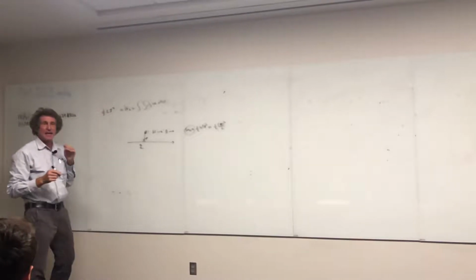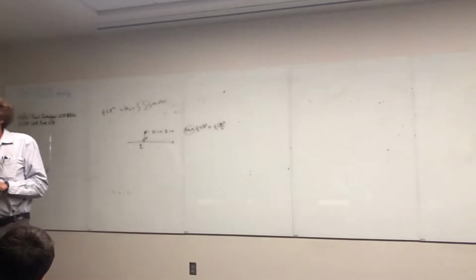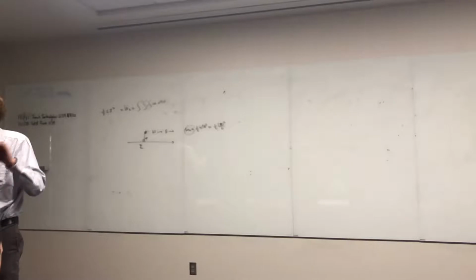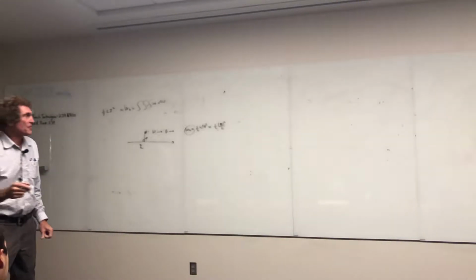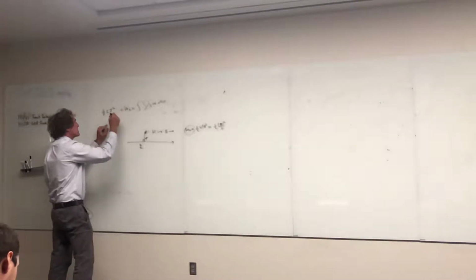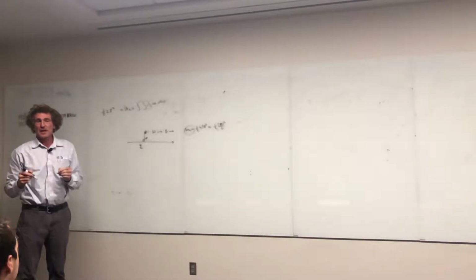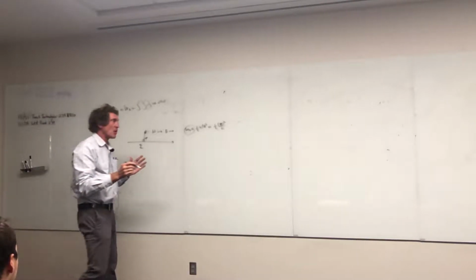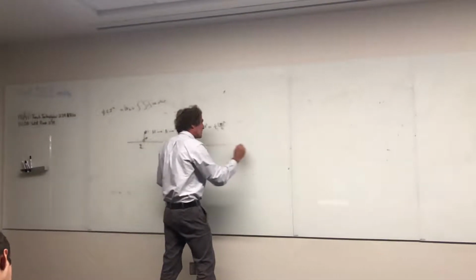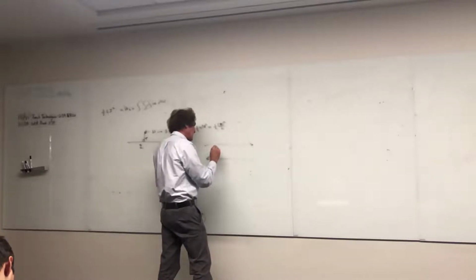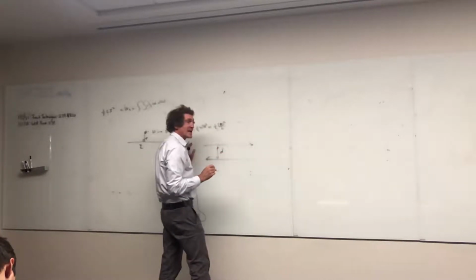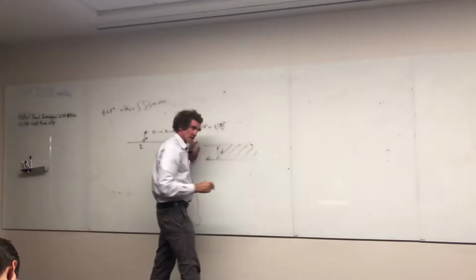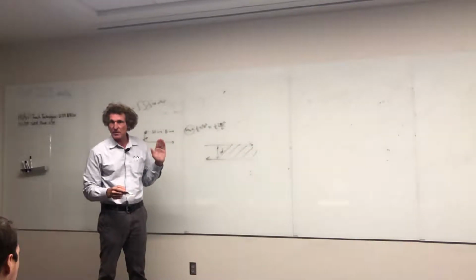That's the total magnetic energy for an inductor. Follow me on this? Do you all remember that formula? 1/2 Li squared was the magnetic energy of an inductor. And therefore, if you knew the current, you could multiply by 2 and divide by I squared, and you could find the inductance. Now, here's the problem. Almost always, if you have two straight wires like this separated at a distance d, we can get the inductance by using the flux linkage method I mentioned last time, right? By finding the flux link between them.